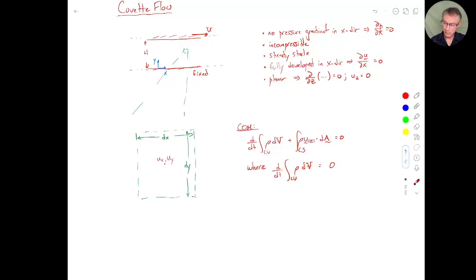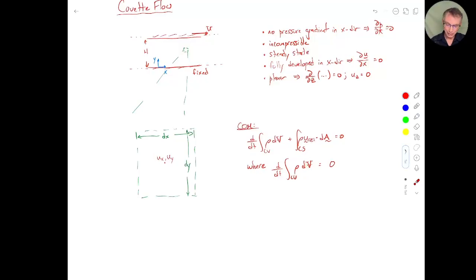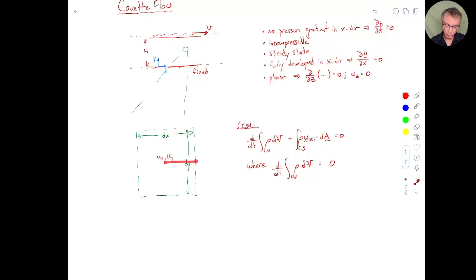And then I'm going to write down what the velocity is in the x direction as I move that direction some small distance. As I go from the center to the side wall here, I'm moving a distance of 1/2 dx. It's just half of the dx here. And I'll write down what the x velocity is over on that side. So the way we write that is it'll be ux, that's the velocity I start with here. And then I'm going to add in how much the x velocity changes as I move in the x direction.